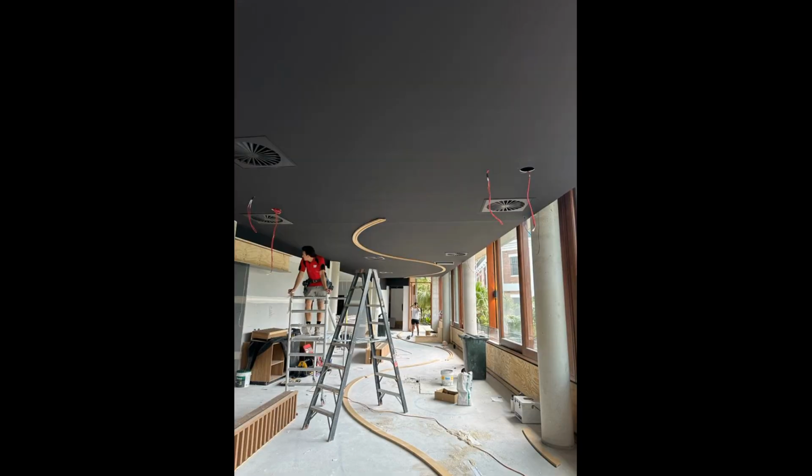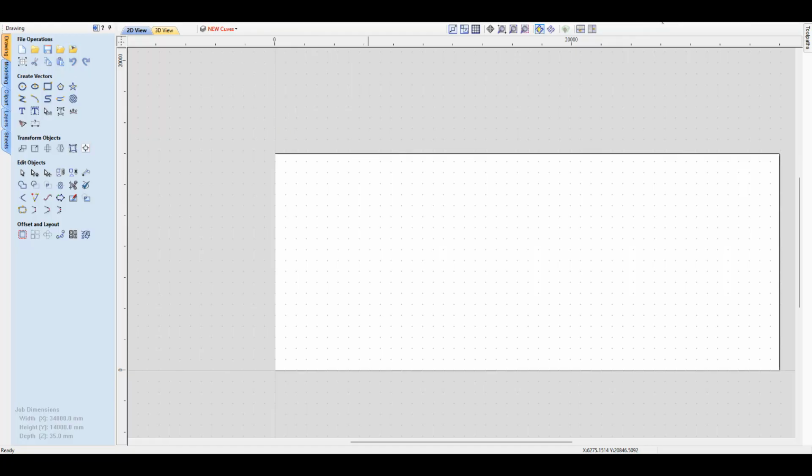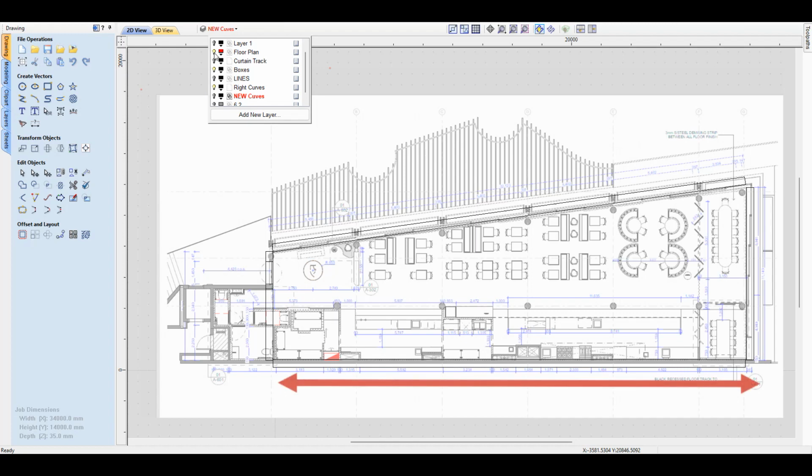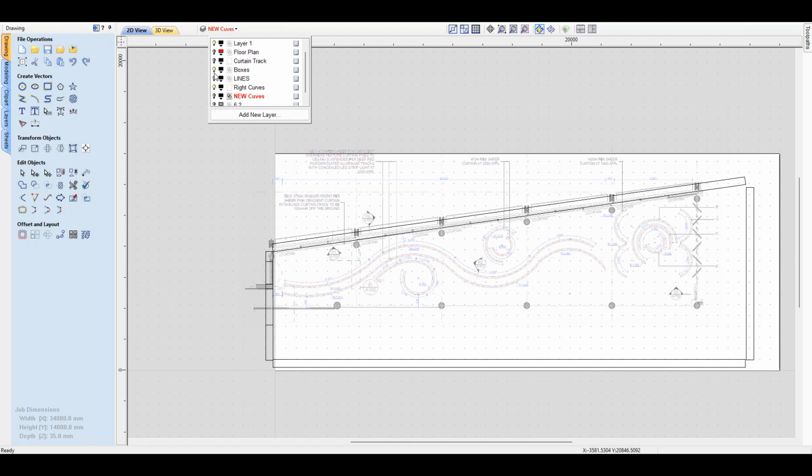Easy, right? No pressure. First step is, how do I get the correct measurements and lengths into the Vetric Aspire software? Now this is how I figured it out. The first step on how to get the correct lifelike scale of the restaurant into the CNC software. I knew the restaurant was approximately 33 meters long, and I imported the floor plans into Vetric Aspire as a bitmap image and scaled the full-size restaurant to the little blue scaling lines that were on the floor plans at the time.